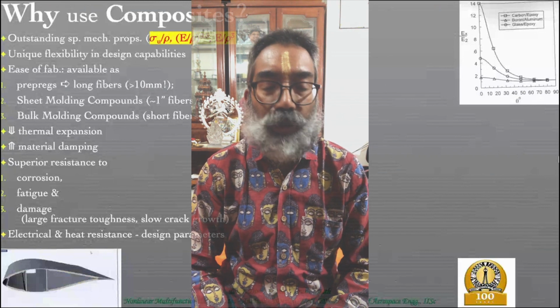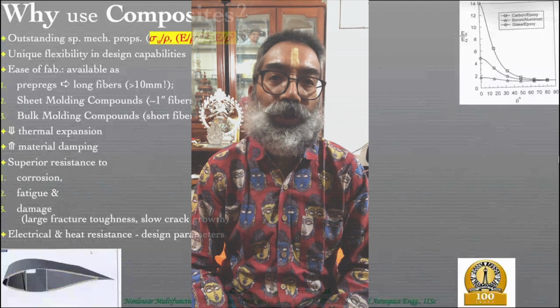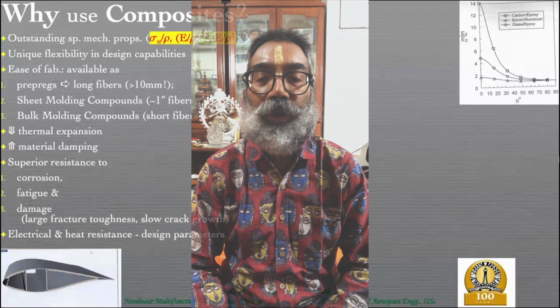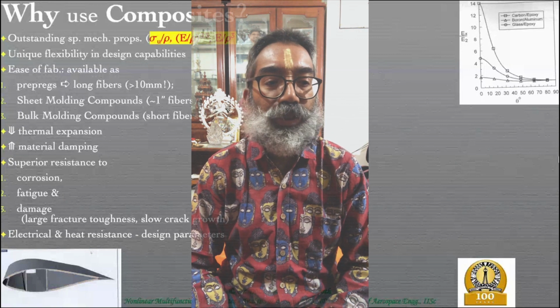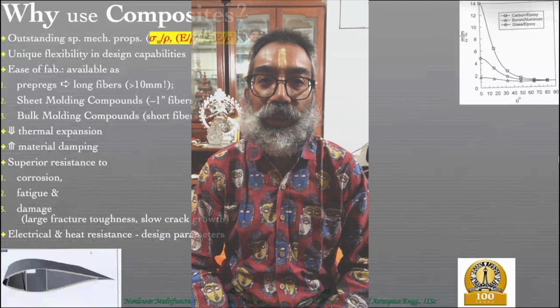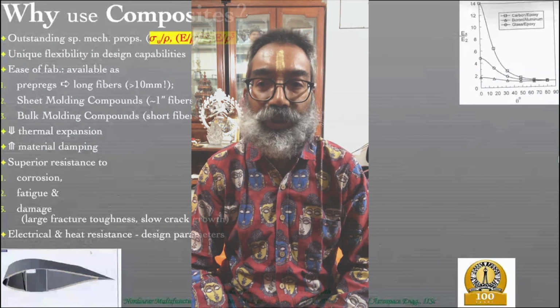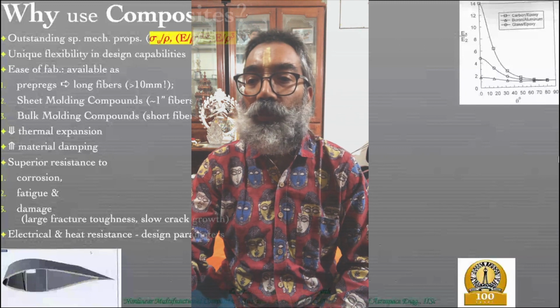And in terms of damage tolerance, we're looking at the ability for it to retard crack growth because of the fibers bridging the cracks in the matrices, and also the larger fracture toughness that we discussed relative to a particular question that we had from one of the students as well.